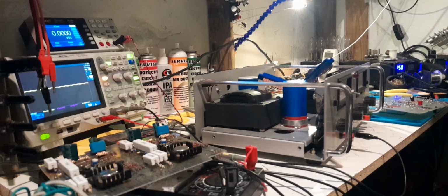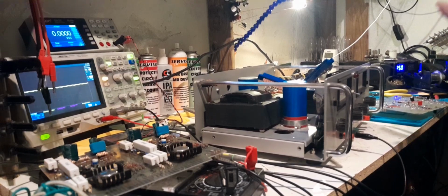I think the best bet is to have a look through my inventory and find an op-amp that matches the LM301 a little bit more, and just look, it's not going to affect the voltage accuracy, the way this thing's done, because it's voltage. So the thing with constant current circuitry is you're sensing voltage across a current shunt resistor, so it's a very small voltage.